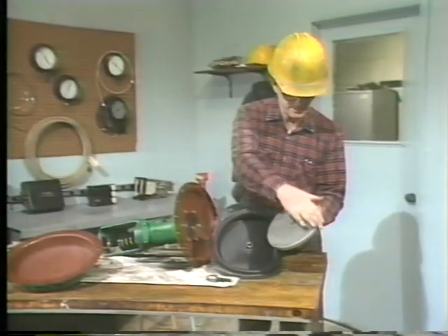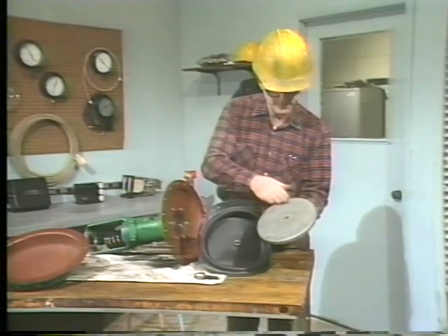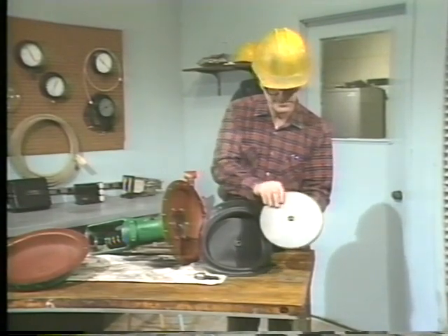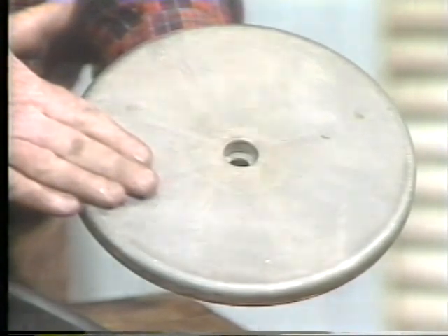The upper diaphragm plate serves as a solid backing for the flexible diaphragm and helps to keep the diaphragm from being damaged when air pressure is applied to it. The plate must be free of burrs that could damage the diaphragm. Any rough spots should be smoothed out with a fine-grade emery paper.